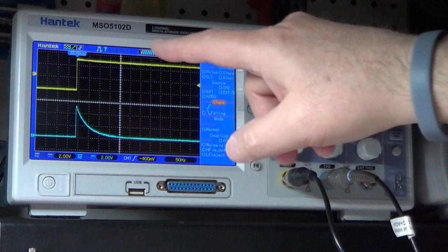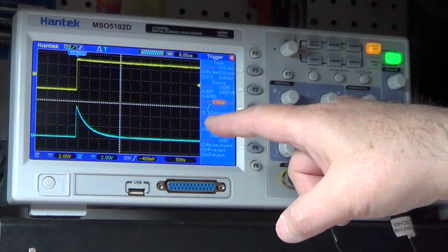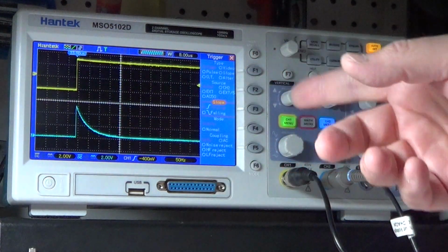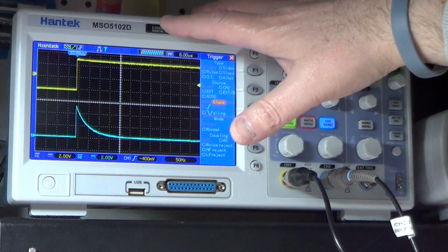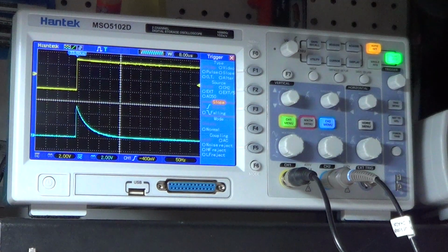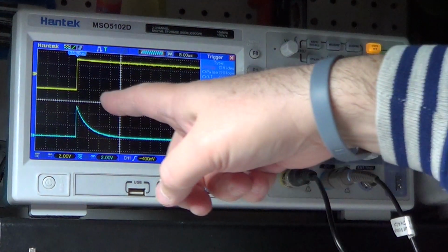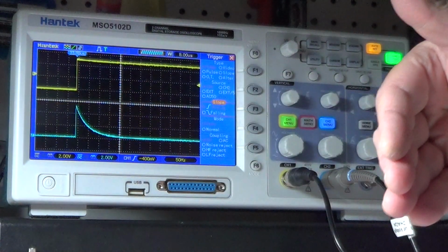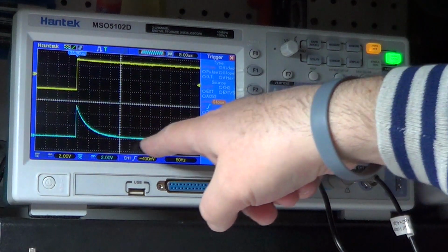So here you can see that as soon as the input voltage changes, a back EMF is created by the inductor to prevent the current from changing. At the same time, the energy provided by the generator is used to increase the magnetic fields around the inductor, and while the magnetic field increases, the back EMF decreases, until once the new intensity of the magnetic field is reached, the maximum intensity, the back EMF goes to zero.